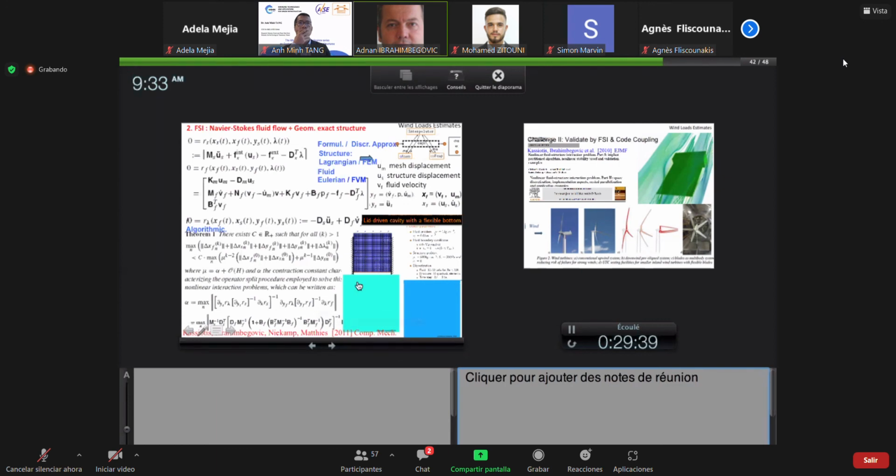This is one of these benchmarks that we use, driven lid cavity flow. In other words, you just put the shear pulse, which is varying in time, and normally the edge of this box is rigid, but here you have a very, very flexible membrane. So you can see what it does. These are kind of streamlines. The membrane is deforming very heavily, and this is the way how we control pressure. You typically have to put the pressure outlet in one point, and again, the membrane is deforming very heavily.